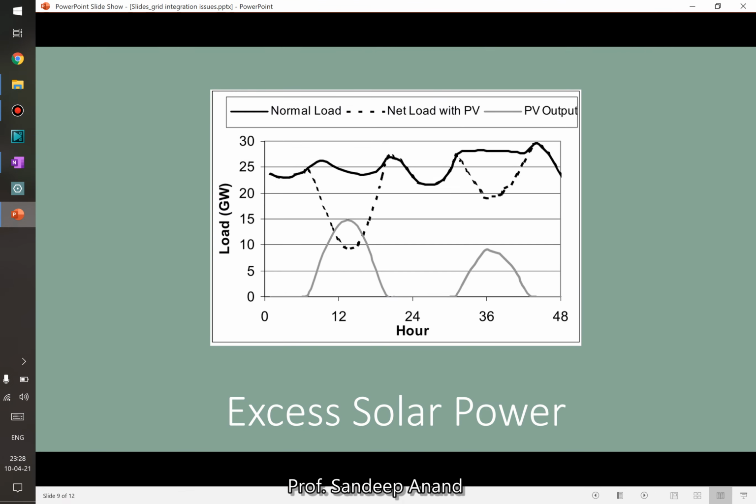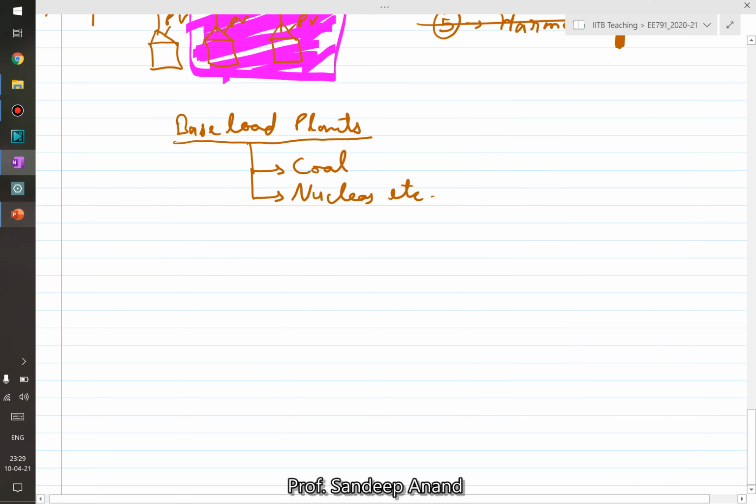Now see this situation. What happens here is, in the afternoon, the power demand of this particular network has reduced. Imagine a similar thing happening with the neighbor places also, with the nearby places also. So in that whole region now, the demand has reduced. Now the question comes that the demand might go below the base plant running capability. The base load plants cannot be ramped down very fast. Moreover, they must have a minimum load for them to continue to run. There are quite a few challenges.